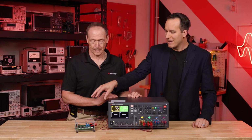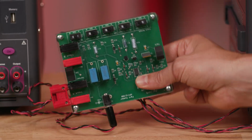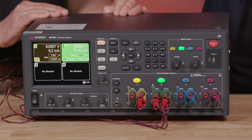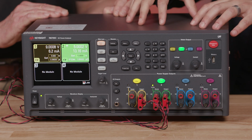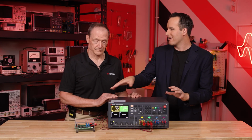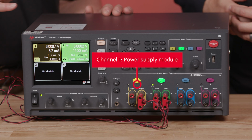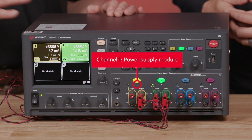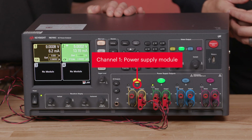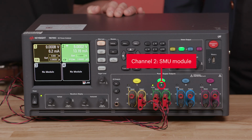So you have a sample IoT device, which is going to have a low power range and a high power range. Correct, yes. This is both powering it, sourcing power, and measuring, hence the source measure unit configuration. Can you talk me through what waveforms we expect to see coming out of this device? Right, so I actually have two modules in here. The first is a power module, the basic power module that's providing 9-volt input to my device here. And then I've got the SMU module connected to the output, applying 5 volts to the output.